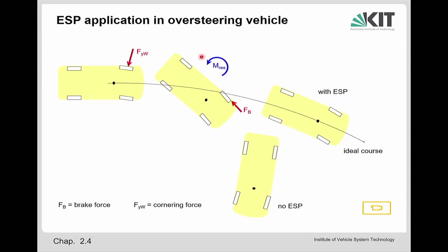This means the oversteer tendency, which is caused by a weak side force support on the rear axle, is reduced. So more side force on the rear will give better control of the car. Also, less driving torque reduces the speed of the vehicle, which means less centrifugal forces. Also this helps.